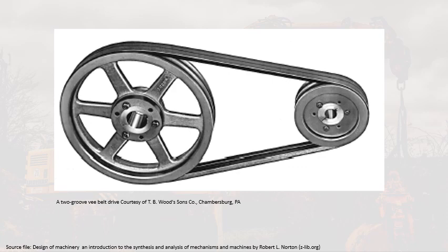A constant velocity transmission, as used in a number of automobiles, is also a V-belt and pulley device in which the pulleys are adjusted in width to change the ratio. As one of the pulleys widens, the other narrows to change the relative radii of the belt with the respective V's. The belt circumference, of course, remains the same.